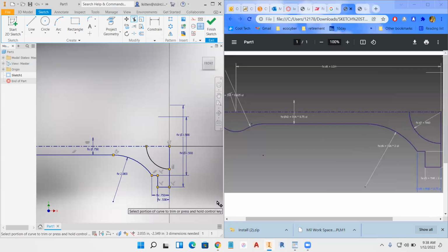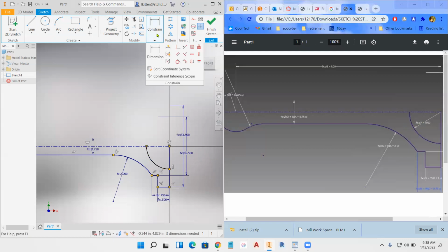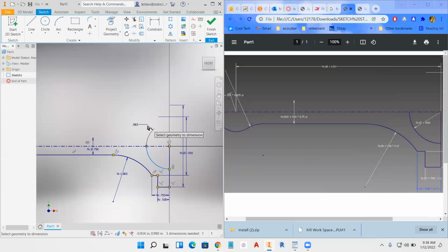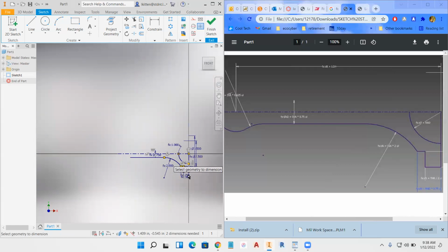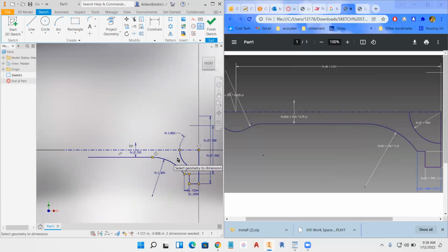Okay. All right, now go ahead and put your dimension on there, and it should just be rad. Nothing fancy. And you could have dimensioned the circle too by right clicking and changing over to radius dimension. That would have worked as well when you put it in. But all right, so now that's a rad. So we're still pretty much fully defined. At least everything's the right color.